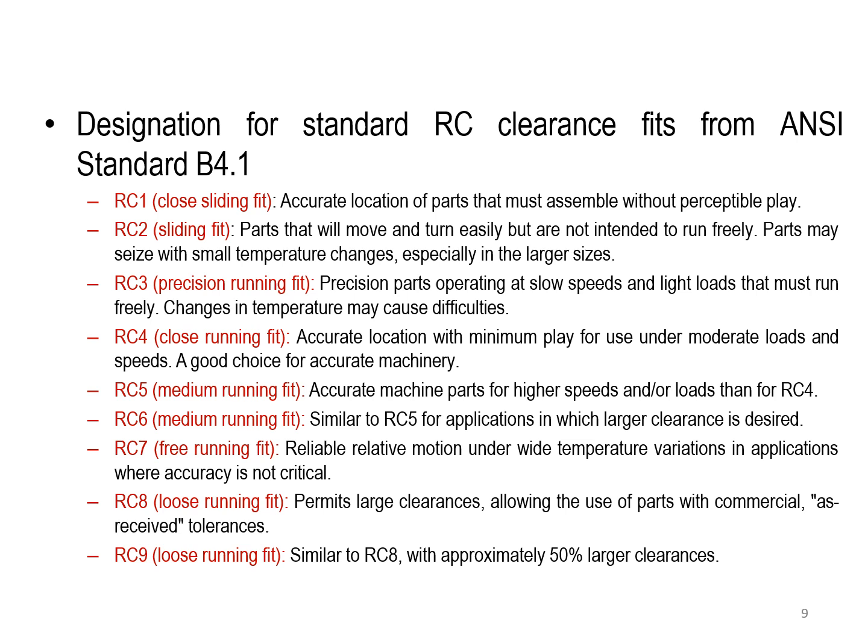The RC4 is going to be the close running fit, and this will be accurate location with the minimum play for use under moderate loads and speed, and a good choice for accurate machinery. So you can see that every time I go to a higher number, the clearance is going to be increasing quite a bit.